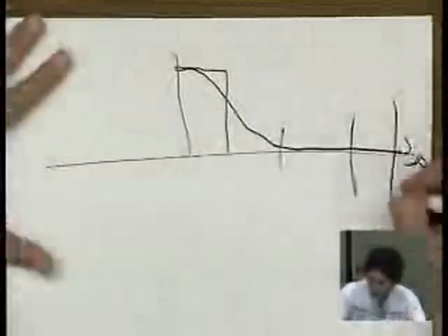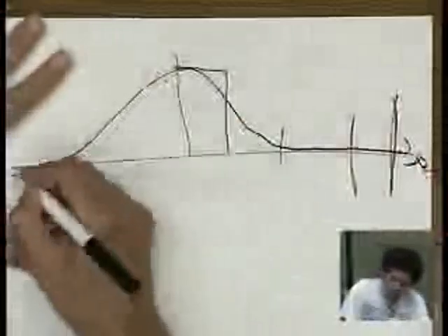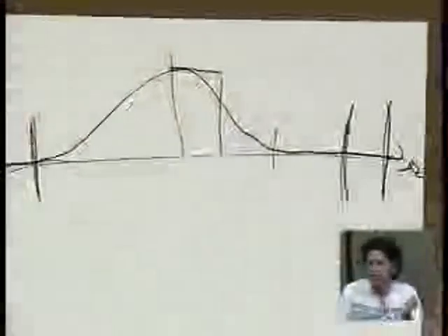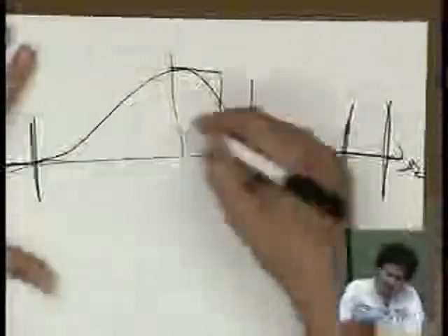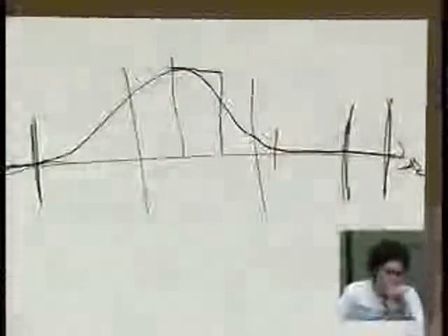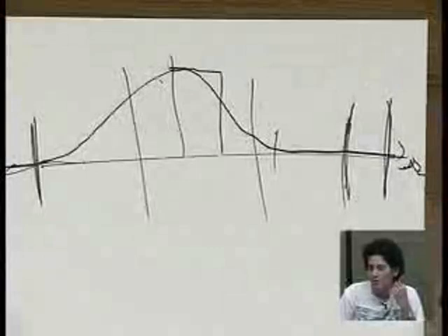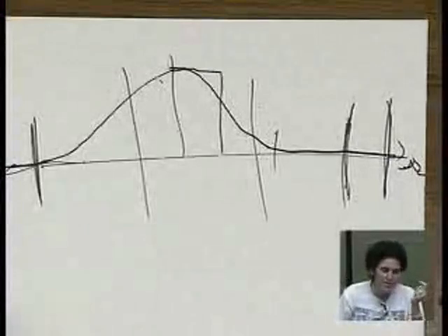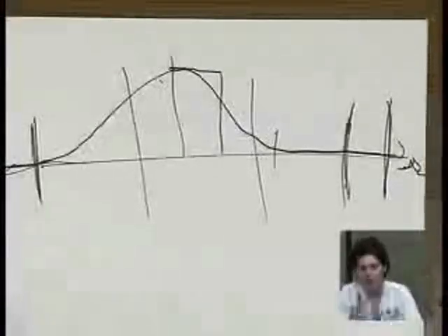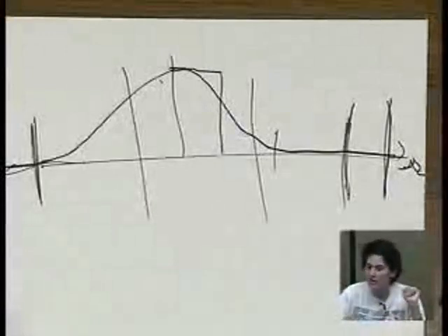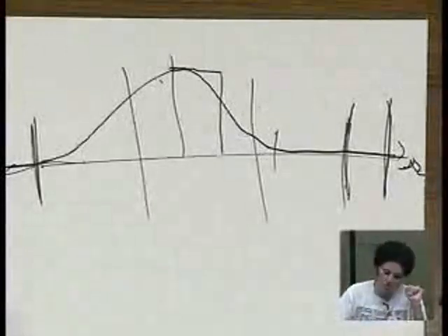Anyway, whatever. You could say here or here, it goes on. You could say, I really want a faithful reproduction, so I'll go further. Or if it is classical, you could say that's good enough, you chop it there, for example. So the answer is, in real life, signals are approximately band limited to a certain frequency. But nothing is ever entirely, truly 100% band limited. The notion of band limitedness is a mathematical invention of our mind in order to be able to process things. And so the more of the spectrum you keep, the more faithful a representation you have.